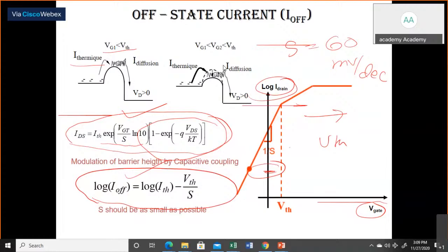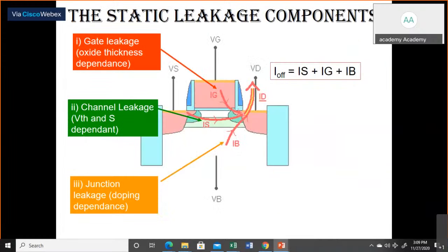So this shows that when we are scaling the device, the leakage current is going to increase. That is a problem of CMOS scaling, we can say. So if we talk about the scaling of MOSFET, the important parameter is, as we know from the previous slide, the leakage current will increase. But what are the different leakage currents possible in a MOSFET?